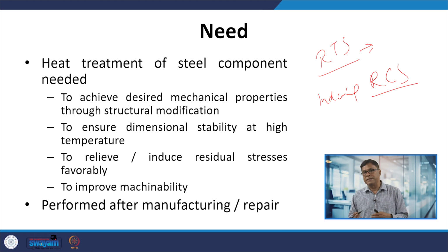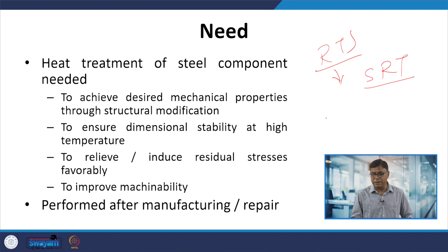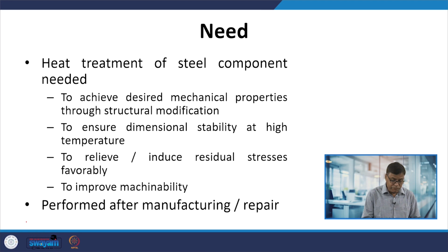Okay. So, to enhance the performance under tensile loading, or under fatigue conditions subjected to tensile loading, there are both possibilities. One, either residual tensile stresses are minimized or eliminated through a suitable stress relieving treatment, or a suitable heat treatment is done so that residual compressive stresses are induced. If that is achieved, then the performance of our component is enhanced, and sometimes even the improvement in machinability